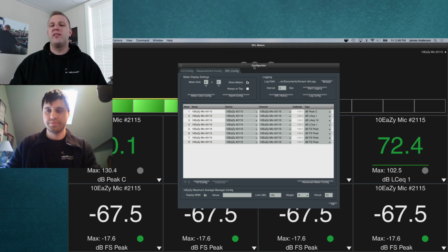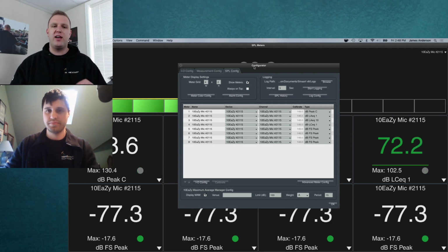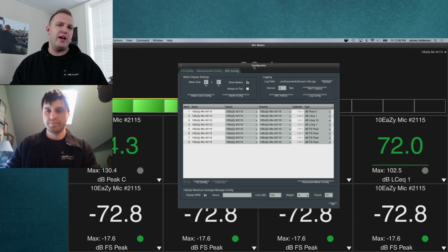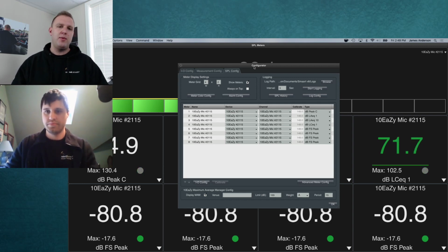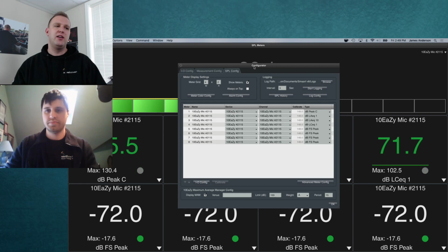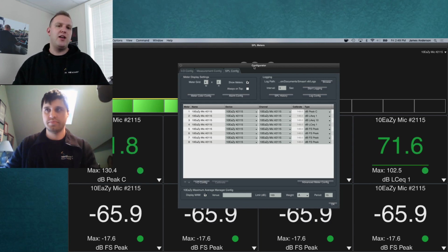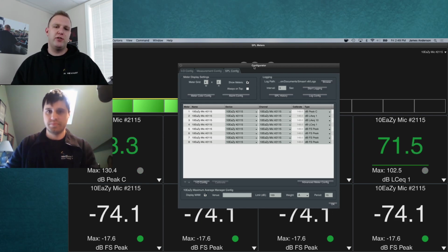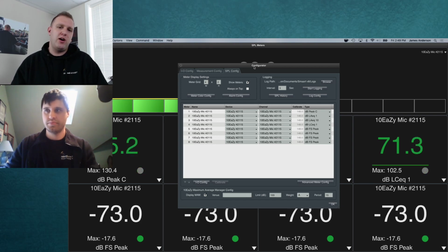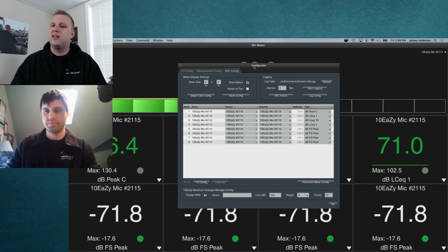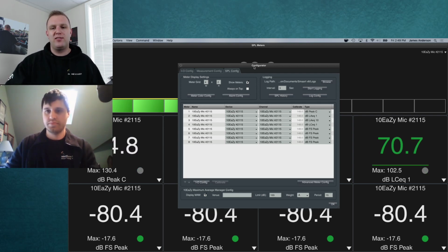I don't think there's one size that necessarily fits all. For me personally, I'm looking at several different values at the same time. I want to know the A weight slow. I want to know C weight slow. I want to know maybe a 10-minute or 15-minute as well. So having one SPL meter, I don't necessarily consider that to be enough, depending on what information you're looking at. To me, the bass ratio of the system, A to C weight, is really an interesting number, and so I want to see both A and C as well.